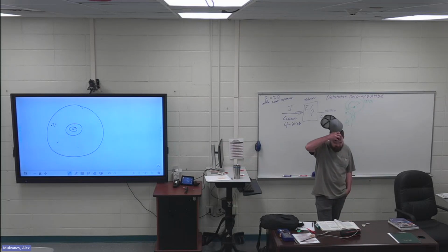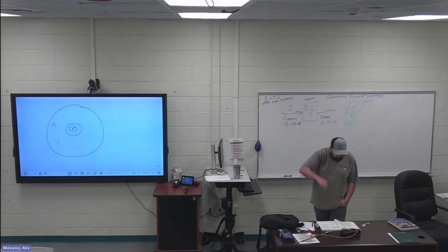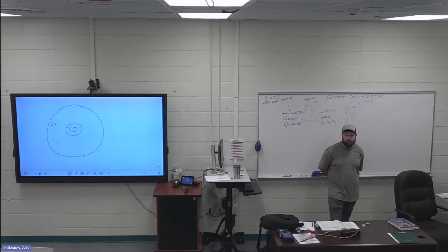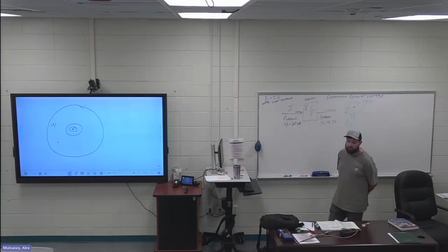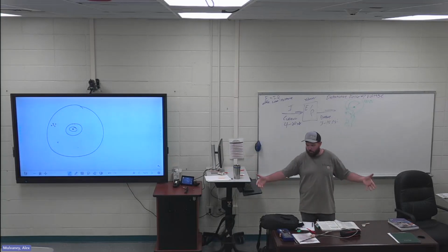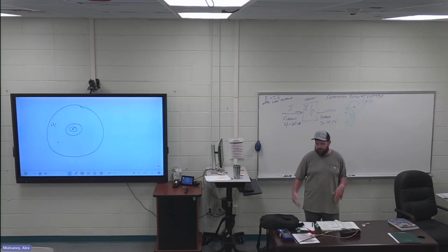First full sentence on page 6 is highlighted. Accuracy is the measure of how close the result is to the accepted standard value. If I have a set point of 100 degrees Fahrenheit for my water tank, that is the accepted standard value. If I'm off of that, it's off accuracy a little bit.